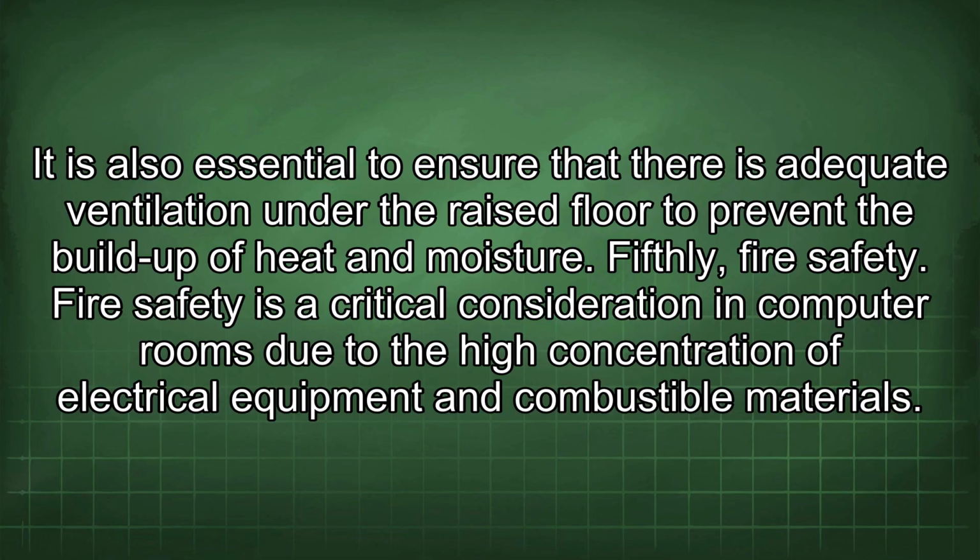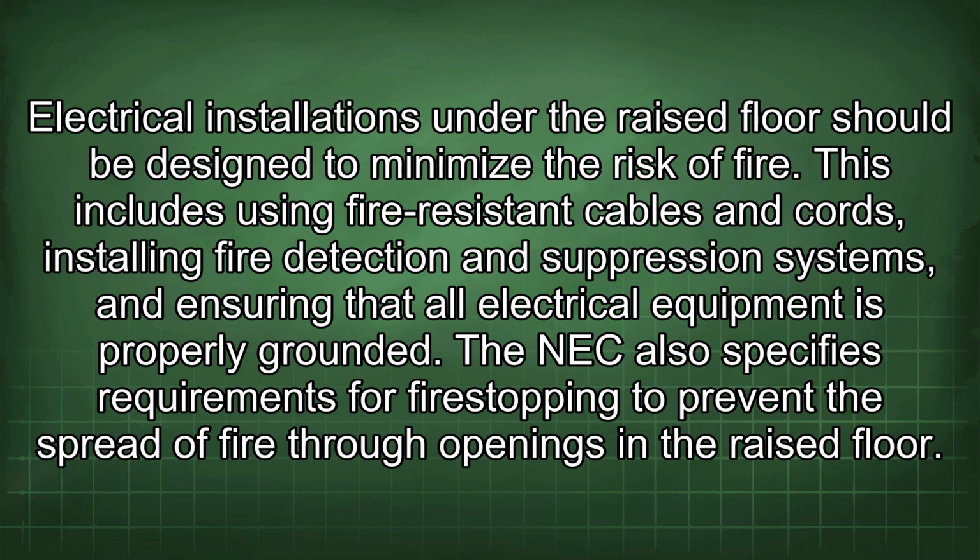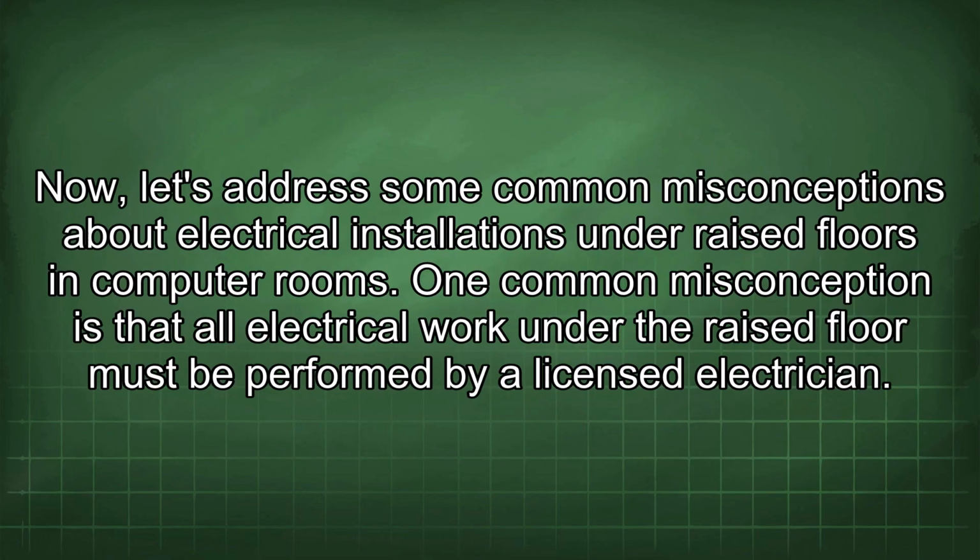Fifthly, fire safety. Fire safety is a critical consideration in computer rooms due to the high concentration of electrical equipment and combustible materials. Electrical installations under the raised floor should be designed to minimize the risk of fire. This includes using fire-resistant cables and cords, installing fire detection and suppression systems, and ensuring that all electrical equipment is properly grounded. The NEC also specifies requirements for fire stopping to prevent the spread of fire through openings in the raised floor.